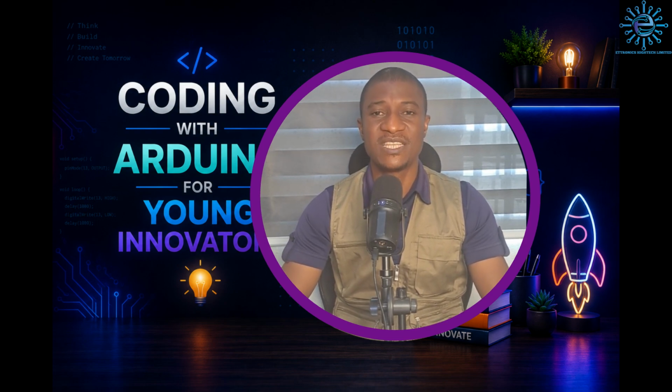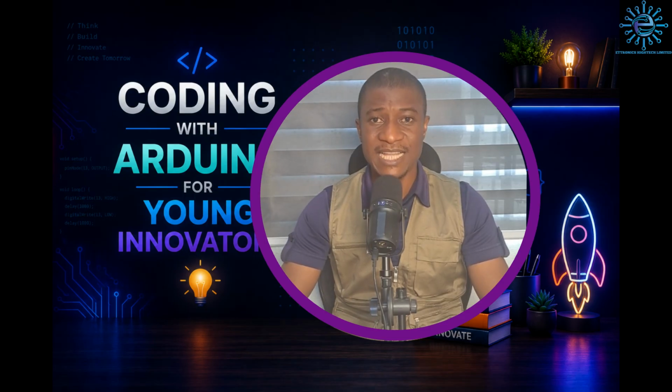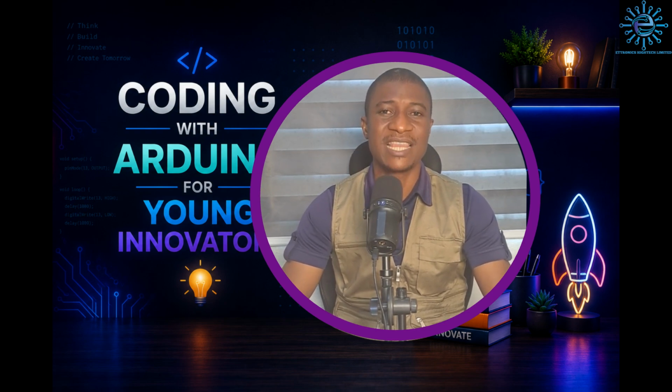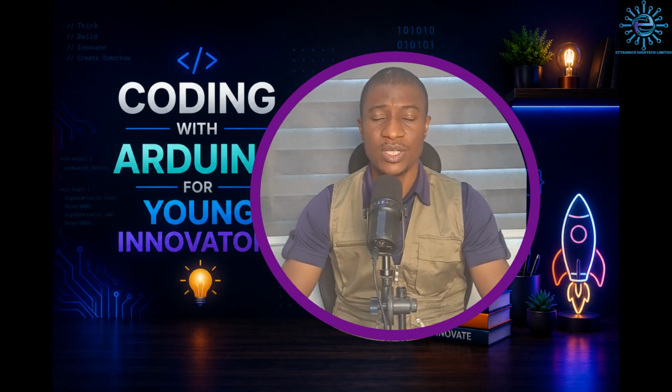Alright, so far in this video, we learned to identify the components needed to build a simple LED circuit. Connect a breadboard power supply and battery holder. Connect an LED, resistor, switch, and jumper wires on a breadboard. Understand the importance of connecting components correctly. Troubleshoot a circuit when it does not work. Identify common problems such as incorrect LED orientation, loose connections, and improperly installed batteries. We also learned that troubleshooting is the process of finding and fixing problems in a circuit.